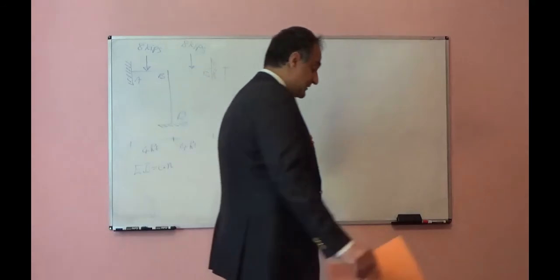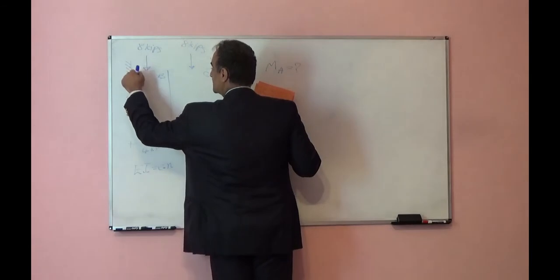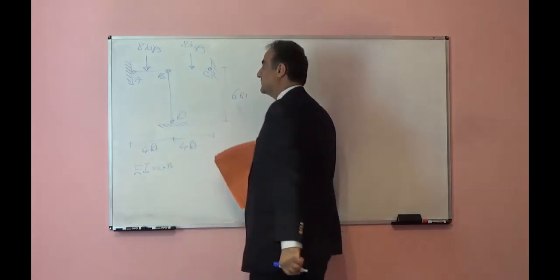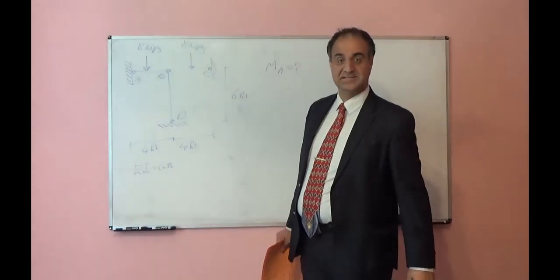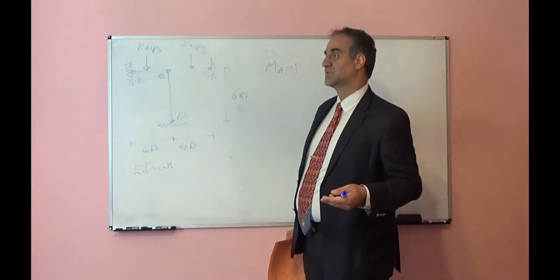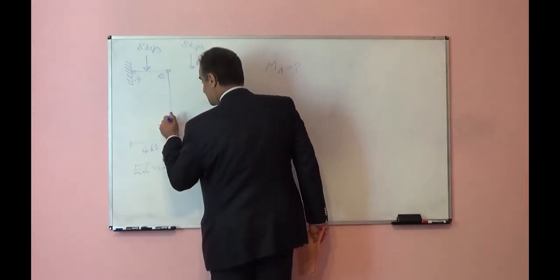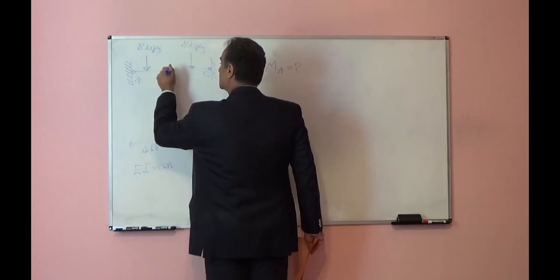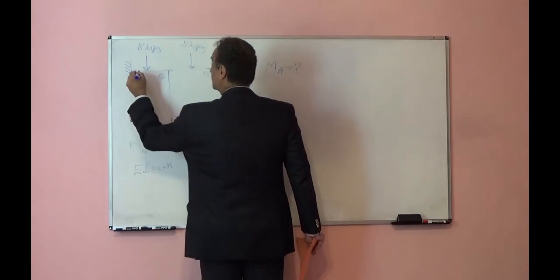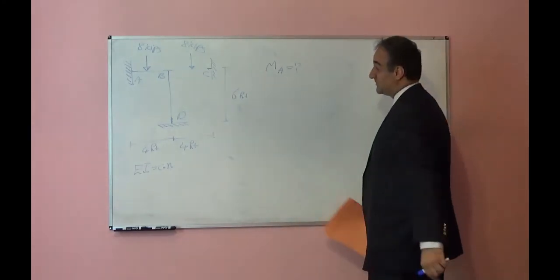In order to find the translational degree of freedom, we should convert all these to pure hinges. If I convert to pure hinges, this system is stable already. I don't need to add an extra member. So the translational degree of freedom is equal to 0. In that case, the total degree of freedom for this system will be only 1. The only unknown we have is theta B.